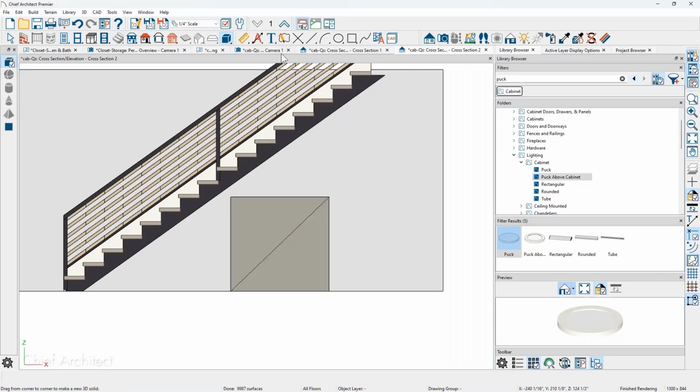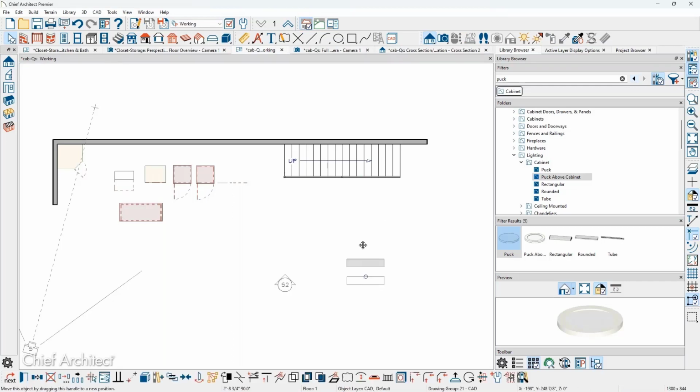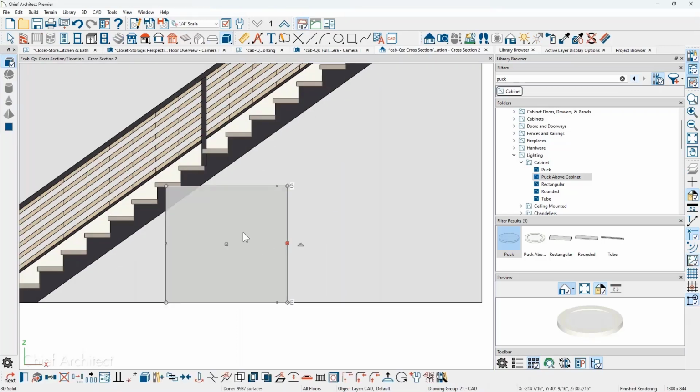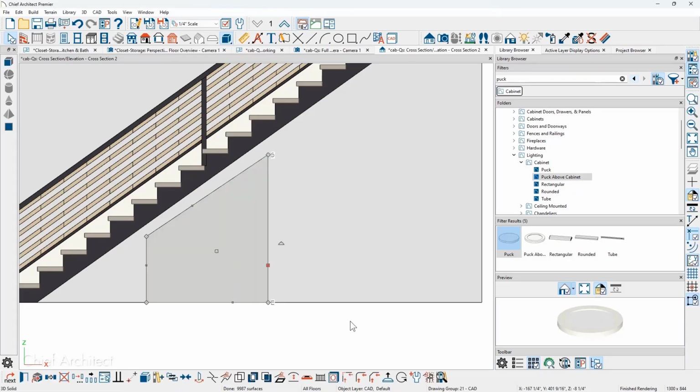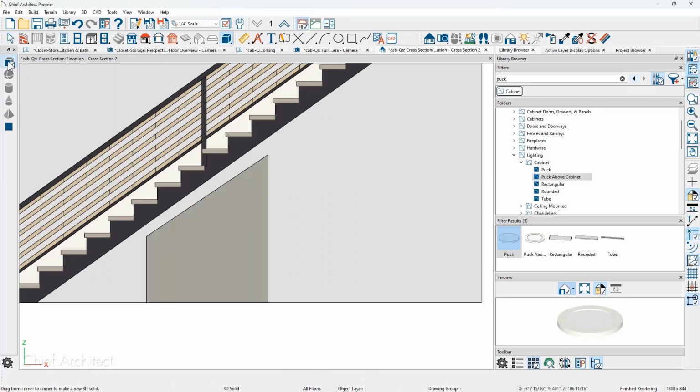And let me pull that view back since it's cropping it off just a little bit. There we go. And so I'm going to just probably pull this down, snug it up just a little bit, and then pull it up so that it's following that shape. And then use the hole tool, right? I can click on this, maybe generate a couple of holes in here, and then do a subtraction and create a custom cabinet this way. So just using the solid tools.